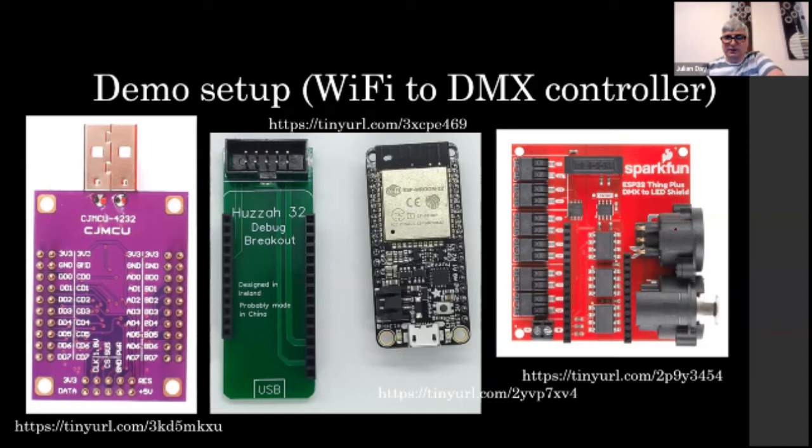So this device has a single DMX bus. You've got some opto-isolators, which are part of the requirement for the DMX standard. You've got the line driver for effectively a 485 multi-drop serial interface, and then a whole load of connectors which I wasn't using, which are basically for driving things like your LED strips. There's a shared clock between each of the 3 channels and a single data pin, and then each also has ground and 5 volts. I wasn't using that part of this device.